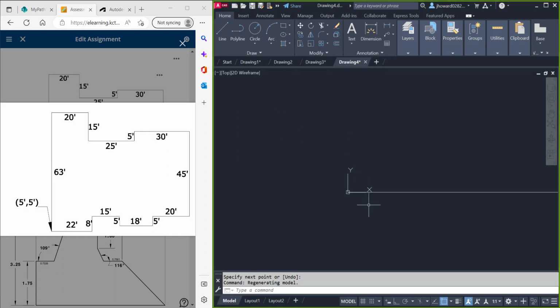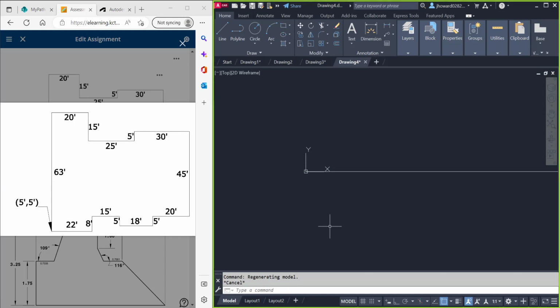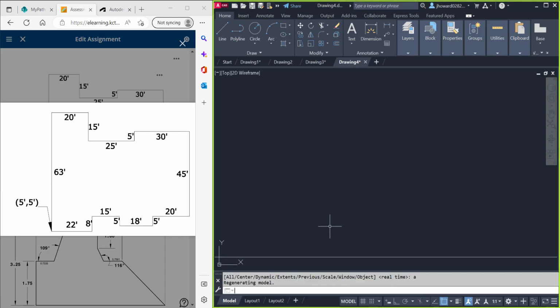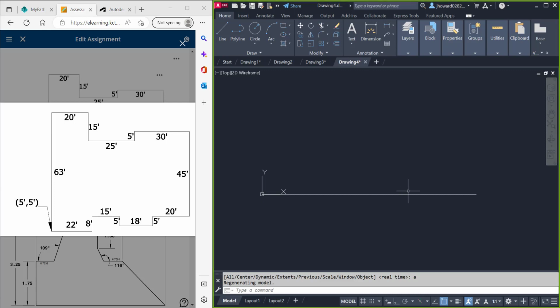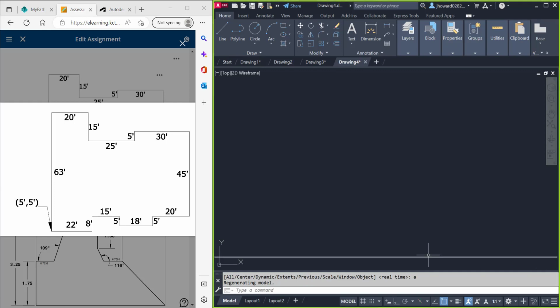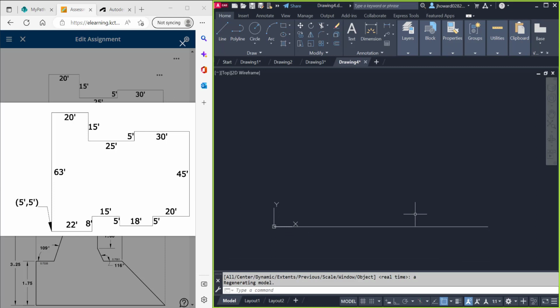Well, that's okay because we can wheel back and forth, but when I first come into a drawing, especially architectural or civil, where something's really large, I always set my limits, and I always hit Z for zoom, and A for all. Or you could have clicked it. And do you all see it kicked me back to where I'm looking at my 100 foot by 100 foot unit. Even though I went 200 foot on this, if I go zoom, enter, A, all, it pulled me back to see that 100 foot by 100 foot. Didn't see all of it because that's 200 foot, but it lets you see the whole thing when you first start drawing. So it really helps with big drawings when you start that.